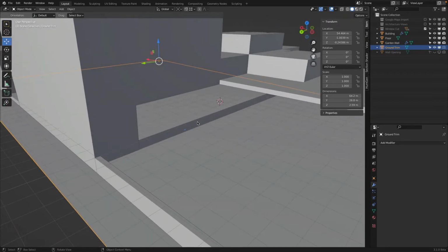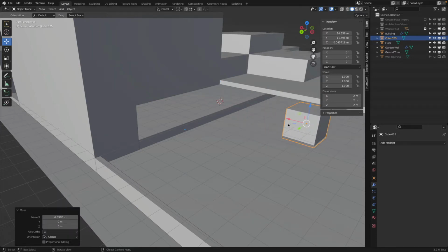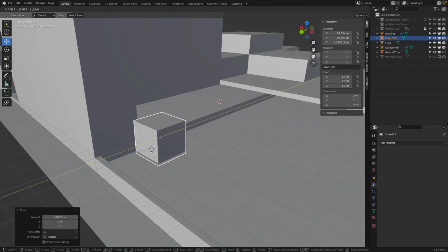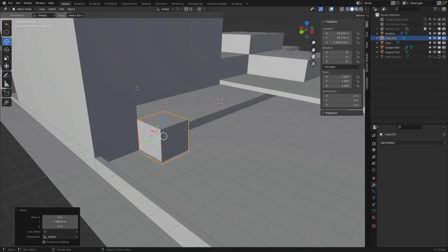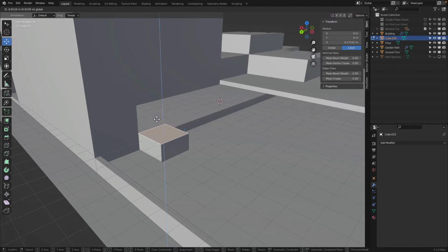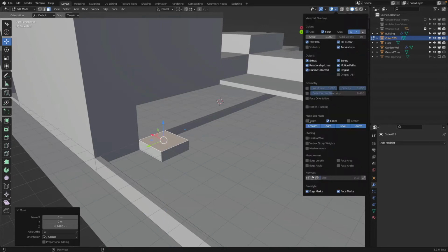Here we have 2 steps. Okay, easy to do. We will start with a cube. This cube I will bring over and then move along the X, hold control and snap, along Y, hold and snap, there. Then I go into edit mode, face select, this one goes down, hold control, snap, and I would like to know the length.